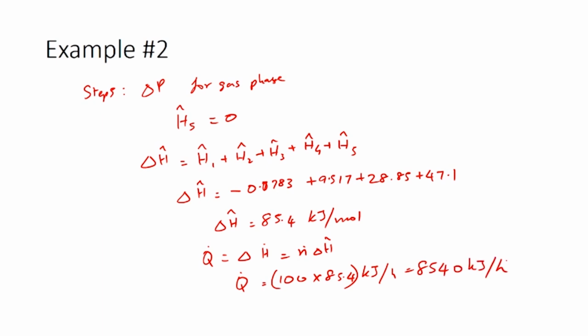In this calculation, one thing you would have seen is that the first step, V cap delta P, the change in enthalpy due to change in pressure for a liquid, was very small compared to all other enthalpy changes. We had 4 processes where we accounted for change in enthalpy. For the last one we assumed ideal gas behavior and calculated the change in enthalpy to be 0.